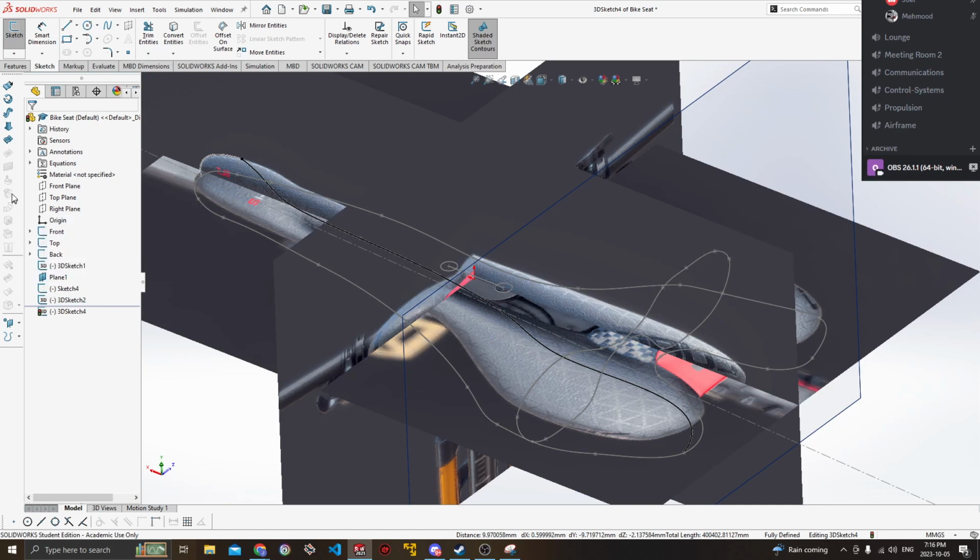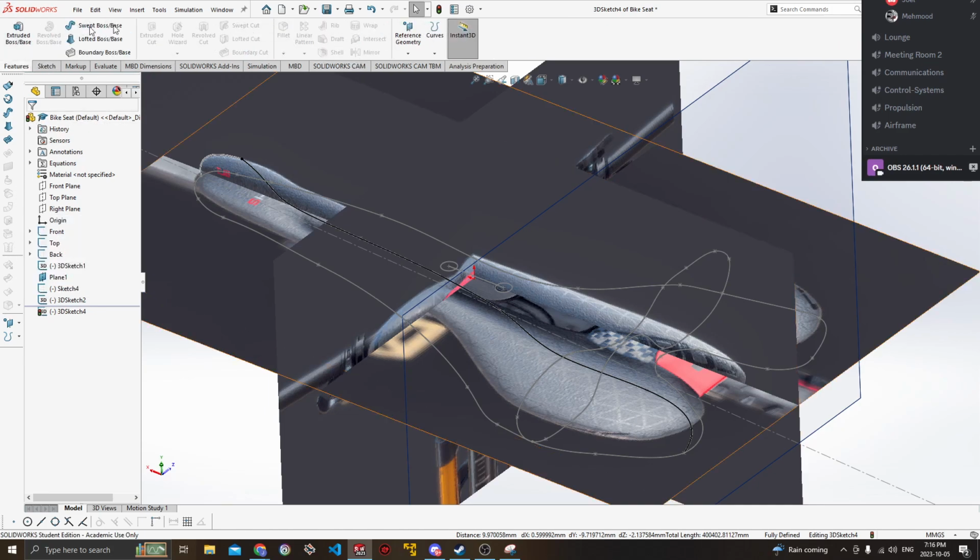It's important to note that normal CAD tools, like anything in these features menu, will typically not work with surfaces. Surfaces are kind of unique. They need to be handled differently. There are some things that do. For example, mirror, patterns, intersections, reference geometry will all work, but anything related to holes, cutting, sweep cuts, fillets, drafts, shells, any of these things will not work on surfaces.